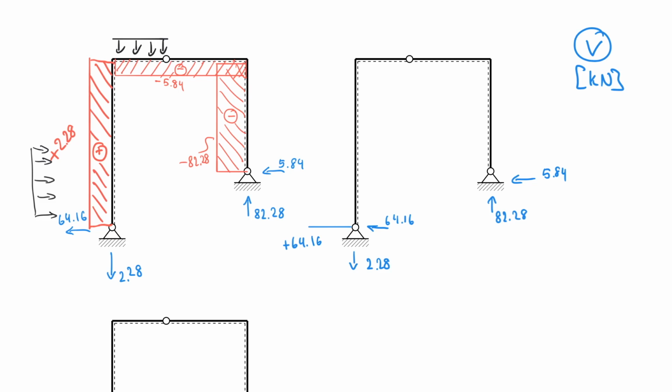So I'm going to pretend that this here is the line where the evenly distributed force ends. And so I have to go down from 64.16 over that distance with actually 20 kilonewton per meter. And so I will pass through 0 actually, and that will become interesting when we talk about the moment diagram.